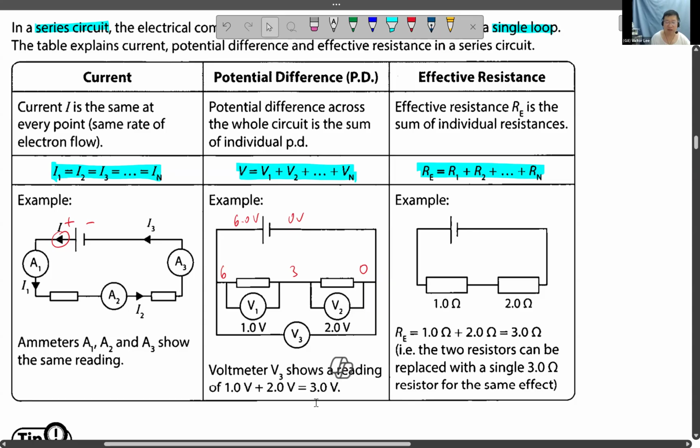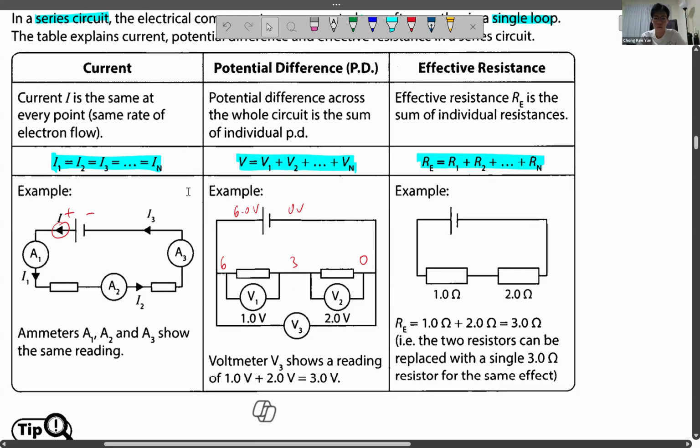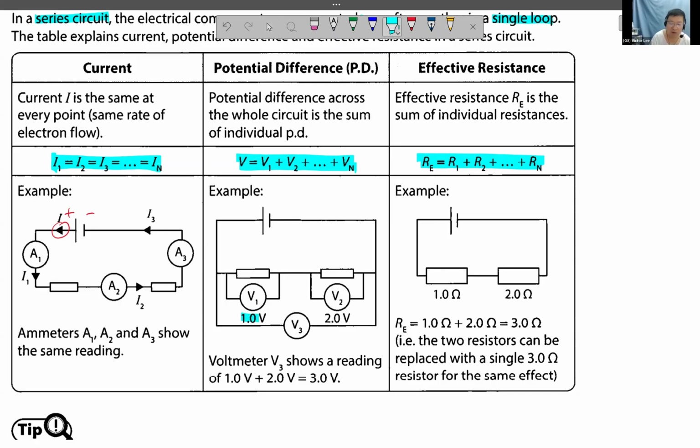Down here, they give you the readings, let's say 1 and 2. If I have 1 volt here and 2 volt here, obviously my voltage here must be 3 volt. Why? The high potential, the positive side, is 3 volt, and the low potential side is 0 volt. So all the wire on this side is 3 volt, everything up to here, all the blue color. Let me put 3 volt here.